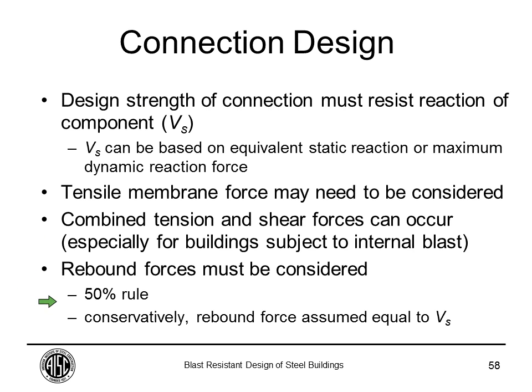And this right here is important. A lot of the components under blast loads, they get hit by the blast load, and they use that internal energy and inertial moment to resist the blast load. But then, even after the blast load sweeps away, they rebound because that energy gets released. So that rebound sometimes can cause the connections to fail. The typical rule of thumb is if your component is remaining elastic, you want to design your connections for the same force inward and outward.